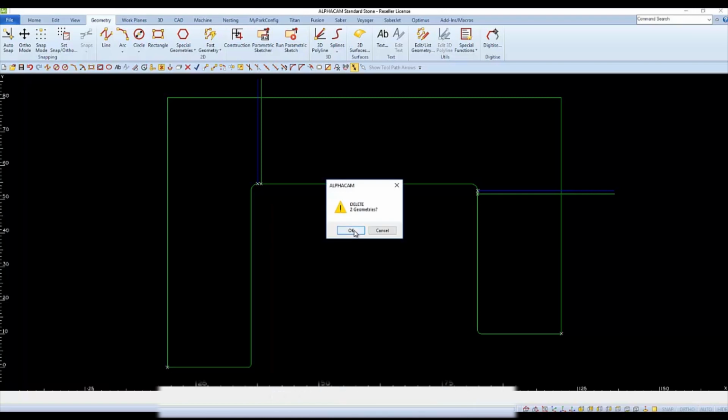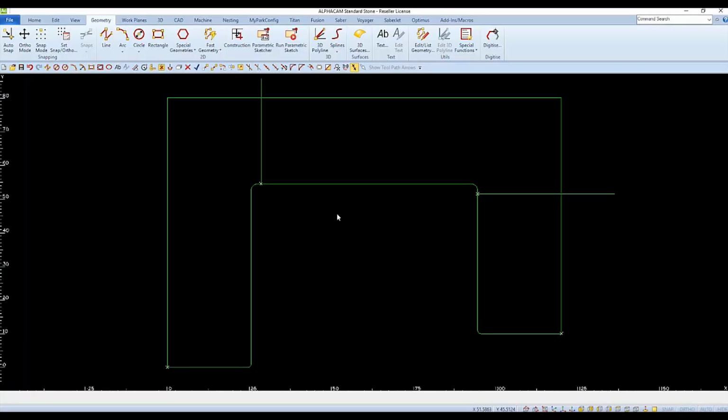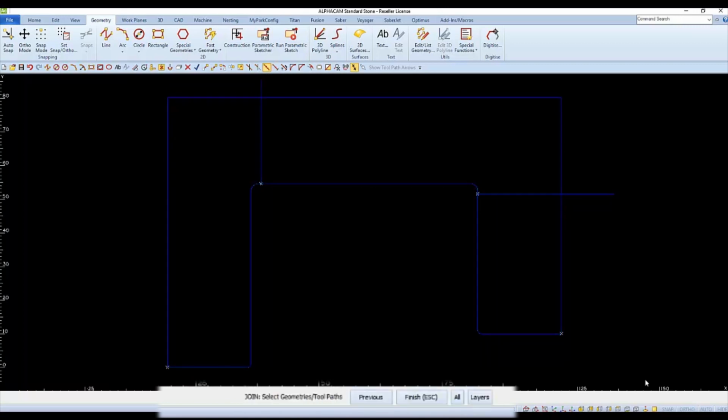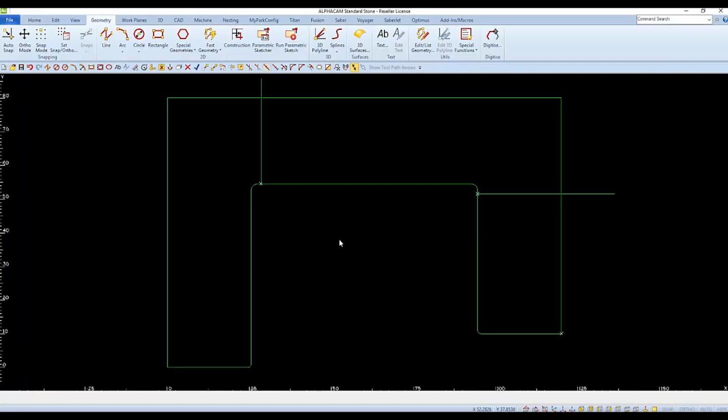And now to separate into pieces. With our countertop and seams drawn, step number 1 is done in our procedure. Step number 2 is to join the perimeter. So choose join, and then we'll select all the lines and arcs making up the perimeter. We only want to join the perimeter. If you select the seams to be joined as well, deselect them by picking them before you finish.